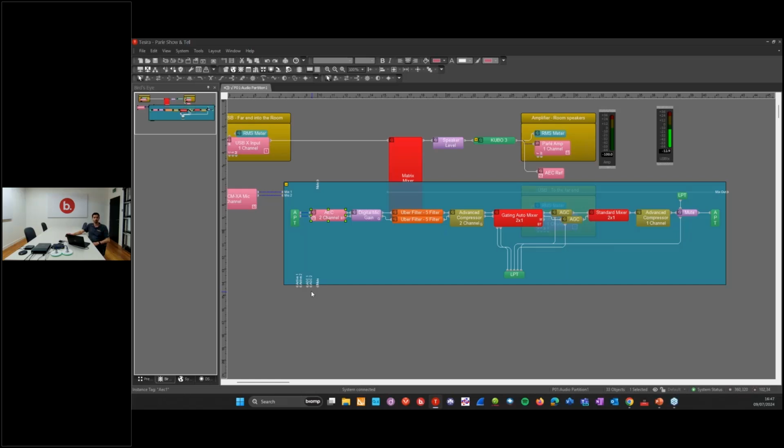Following that, we can't open this block because it's preset. It's a digital mic gain. For the TCM1 dependent microphones, we add 12 dB of gain at this point, and for the X series microphones, the table and the ceiling, we add 18 dB of gain. There is a good reason for that, and that's why it's preset and not configurable: we leave the headroom in the microphone itself. If the far end begins to talk at a high level, say through a ceiling speaker, and it clips the input at the microphone, that would cause problems for the AEC algorithm that needs to deal with that far end echo. So we leave plenty of headroom within the microphone itself, and once it's come over the AVB hop digitally, we can use that makeup gain here.